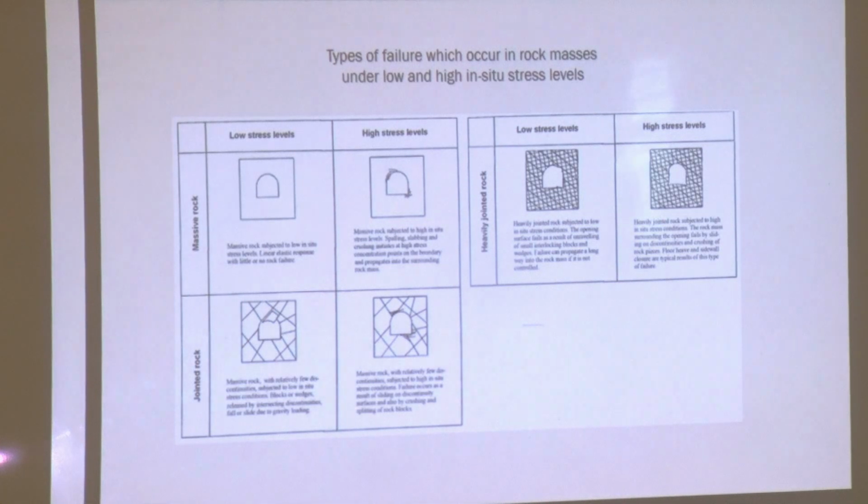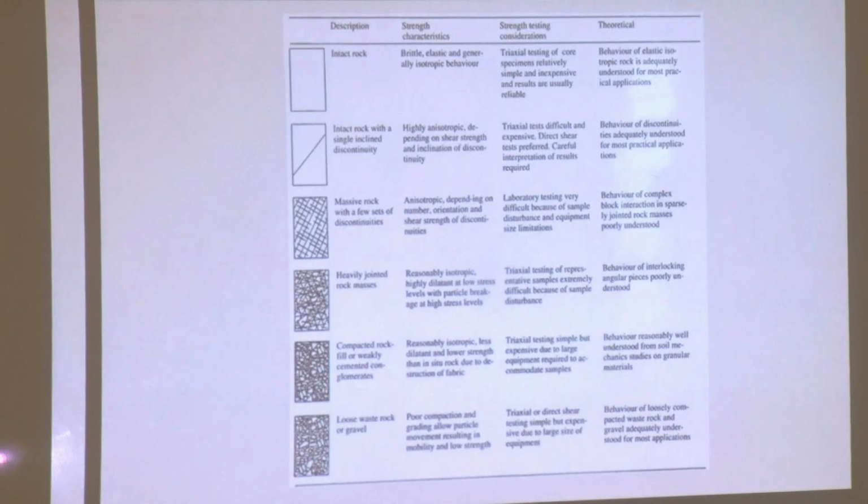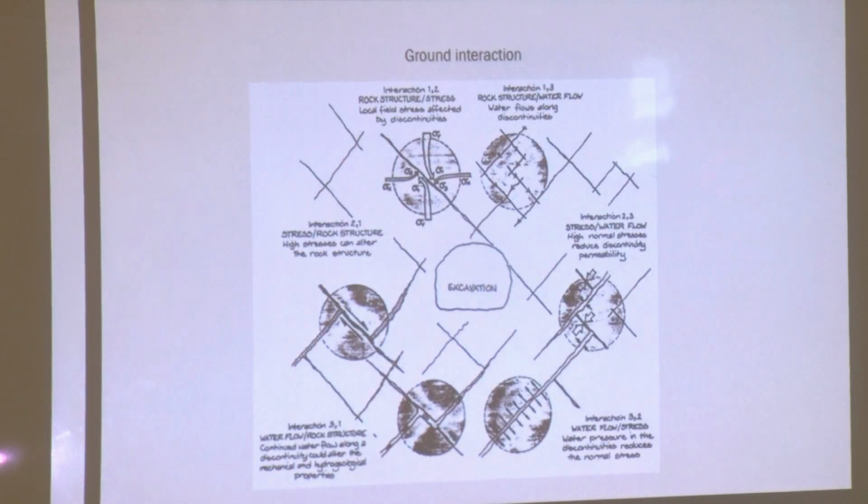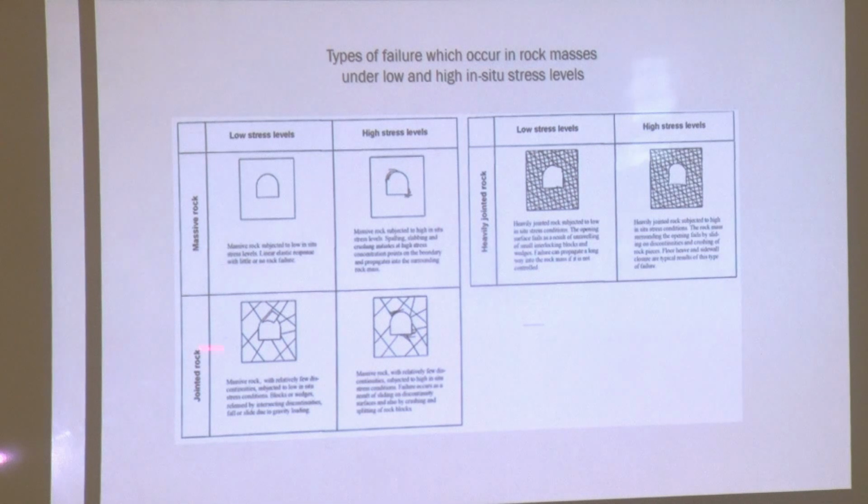Otherwise, now going analytically, suppose we think about the first case: low stress level and a massive rock with no discontinuity, you can model it, no problem. Second one, high stress level but massive rock, it is also possible, you can predict using your numerical method as well as the available elastic approach. But for the other cases, heavily jointed ones, it is very difficult.